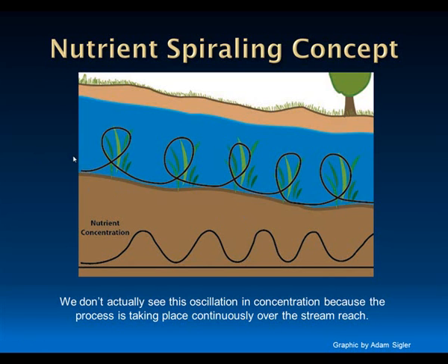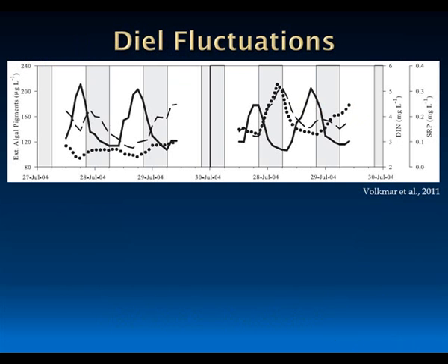So soluble nutrients in a natural stream system with really low concentrations of soluble nitrogen and phosphorus are going to be taken up very readily. Those nutrients are not going to make it far downstream before the plants in the stream are going to gobble them up because they're starving for those nutrients. In polluted systems, things start to behave a little bit differently, and you can actually saturate them, and that's what you've typically done when you have really high concentrations of nitrate, for instance. But this concept is related to what we see with diel fluctuations.